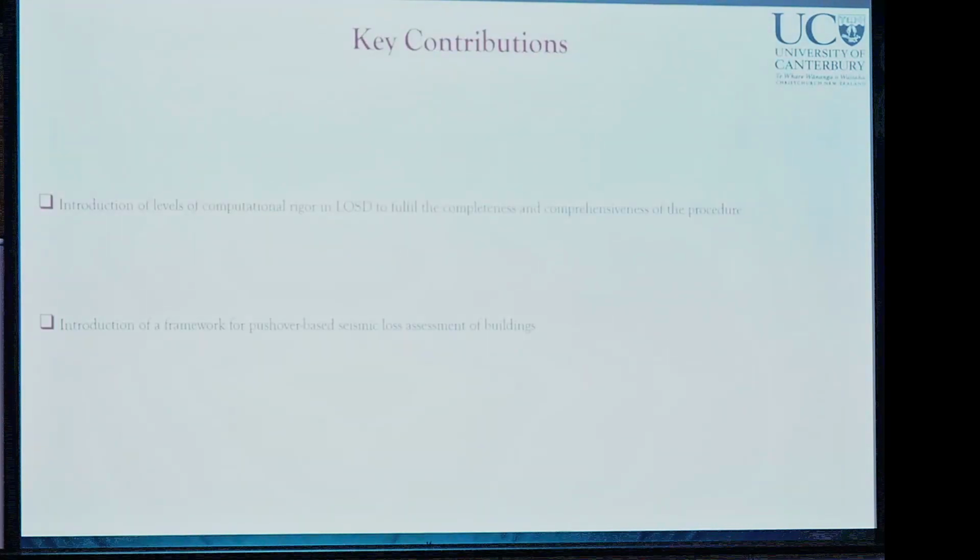Now, if I want to just list key contributions of this part of the research, the first one is that we have proposed different levels of computational effort or rigor for LOSD, so that we have extended the framework of the LOSD, and now we have introduced LOSD as a comprehensive procedure, which can be used not only as a quick method, but also for different buildings with different importance. And also the framework for a pushover-based seismic loss assessment has been proposed.